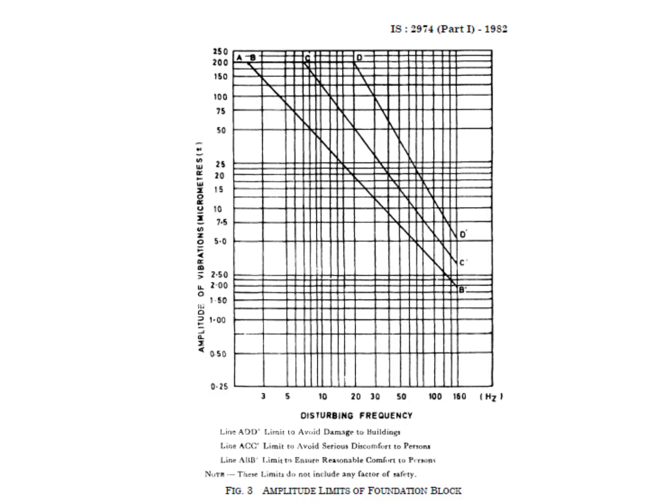Under all circumstances, the maximum upper limit imposed on the displacement amplitude resulting from machine vibrations is 200 microns. This must not be exceeded in any circumstance. So these different curves can be adopted depending on the situation. In any case, there should not be any compromise with the safety of the structure.